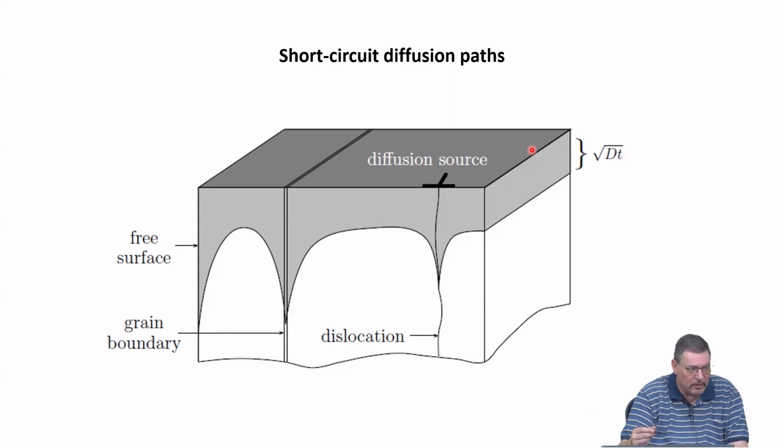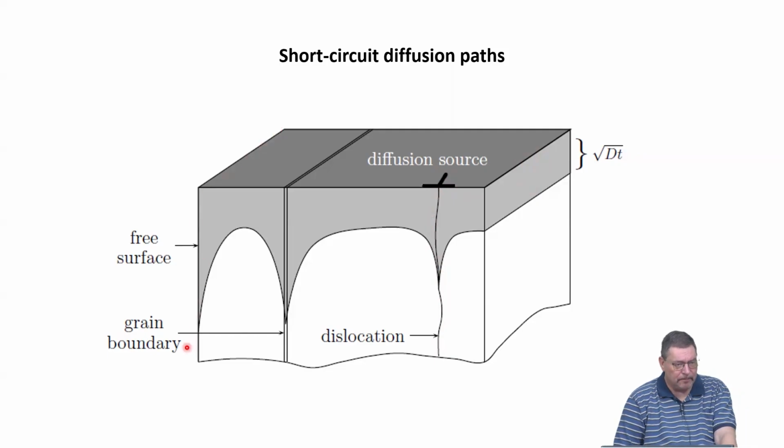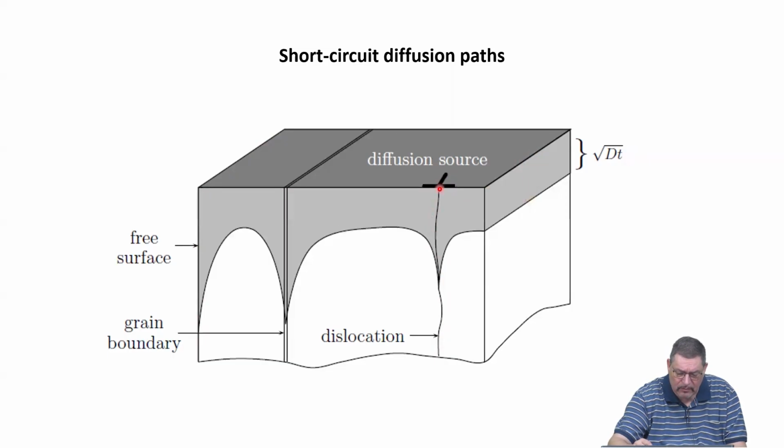take the idea of a polycrystalline material, but we forget about volume diffusion, we forget about dislocation pipe diffusion, and we forget about free surface diffusion. It is easier to neglect volume and dislocation pipe diffusion because they are slower. So we could mentally think we just do an experiment for a sufficiently short time, so we will not see an effect of volume diffusion, we will not see dislocation pipe diffusion, but this one will be faster, so we will see grain boundary diffusion. The point is, surface diffusion is even faster.